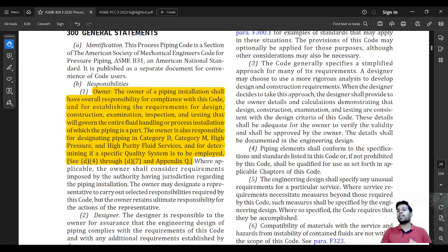In some cases, ASME does provide certifications to manufacturers, such as for pressure vessels you have the U stamp, U2 stamp, and for power piping you have the PP stamp. All of those stamps are gained by the manufacturer by complying with certain requirements, and an audit is done by ASME. But for process piping, ASME does not give a stamping scheme or certification scheme.